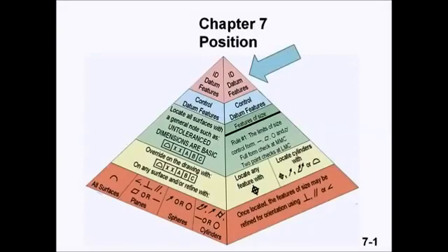Use the GD&T hierarchy pyramid to introduce the chapter by saying, once datum features have been identified and controlled, you have to locate the other features. We now know that any surface may be located using profile of a surface. We also know there's a special group of features known as features of size.